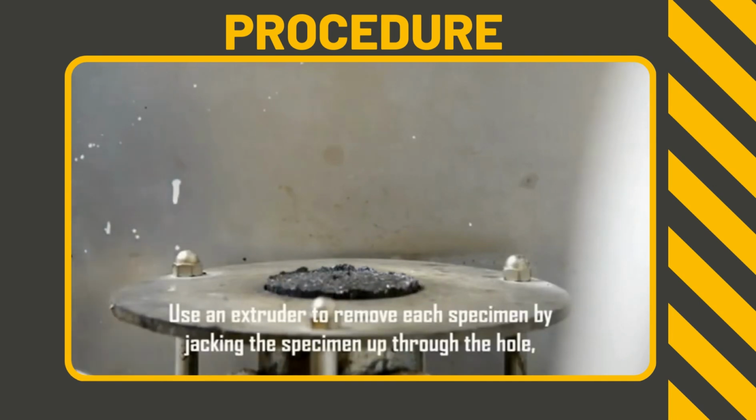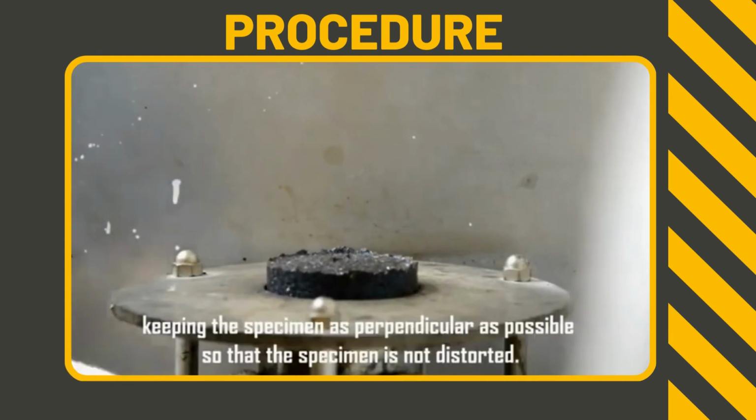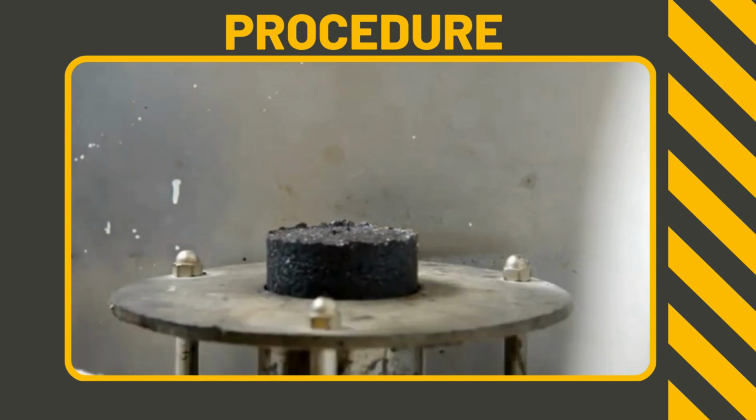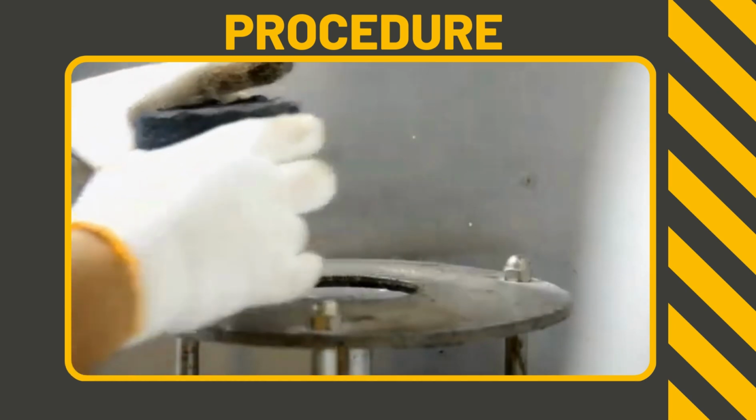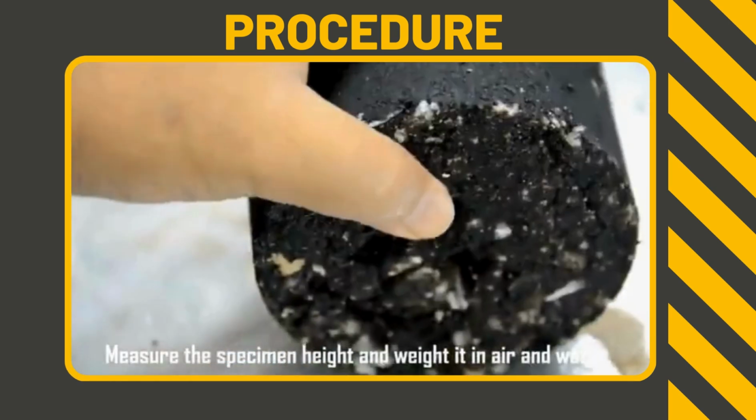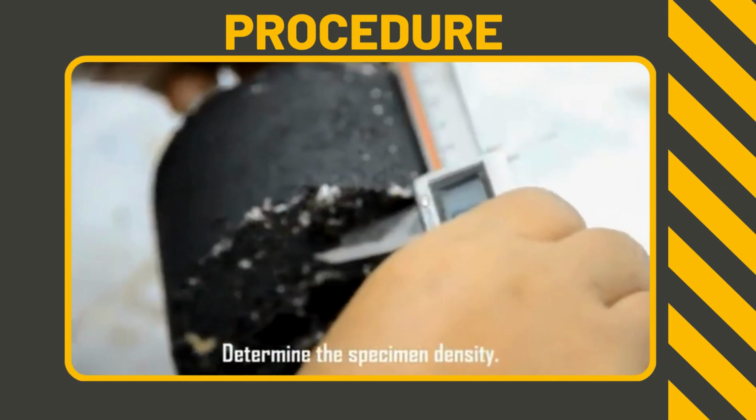Use an extruder to remove each specimen by jacking the specimen up through the hole, keeping the specimen as perpendicular as possible, so that the specimen is not distorted. Measure the specimen height, and weight in air and water. Determine the specimen density.